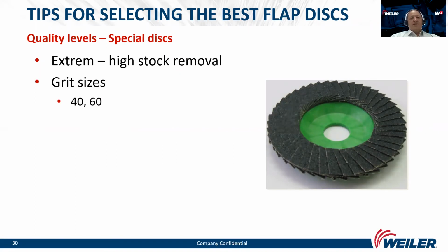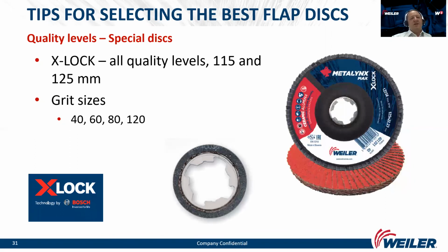Extreme flap discs can be used when high speed and high stock removal rate is required. Low angles of flaps and longer length of flaps allow us to grind aggressively. The angle between flaps and backing pad is as low as possible, and the speed is as high as possible.